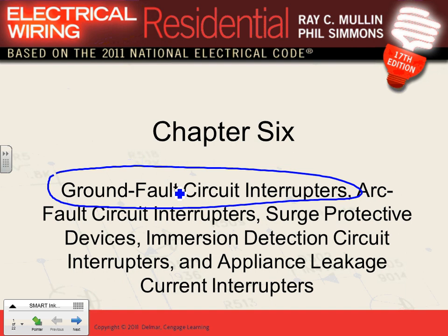The second one is the arc fault circuit interrupter. This device is meant, no electrocution here, to protect you from a fire initiated and activated by an electrical arc. So you have a loose connection there. The loose connection sits there and arcs. If you have some type of combustible things around it, you will ignite the surroundings and create a fire.